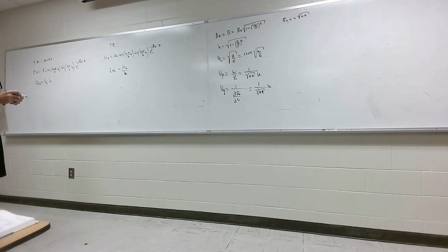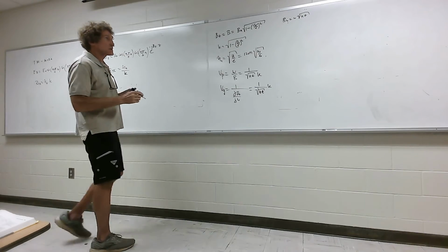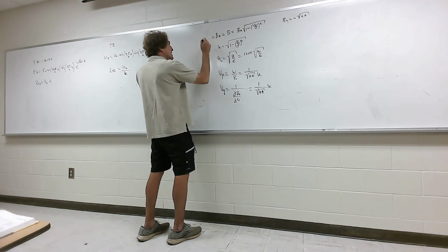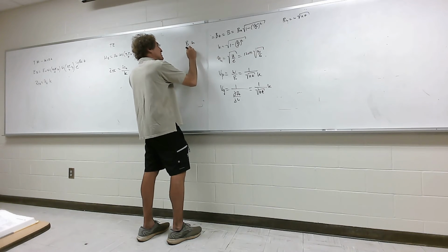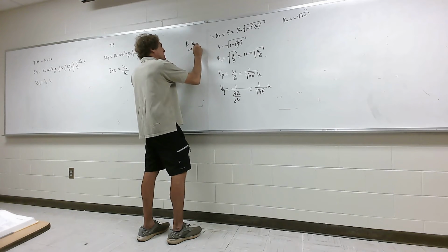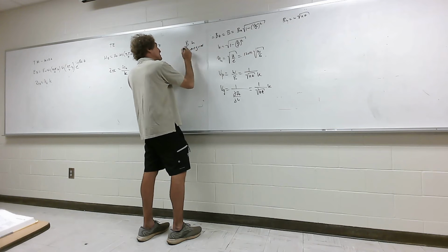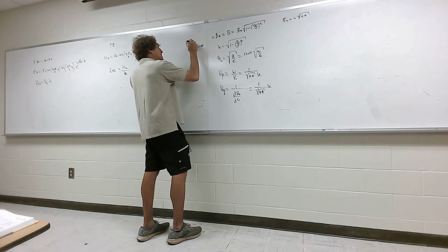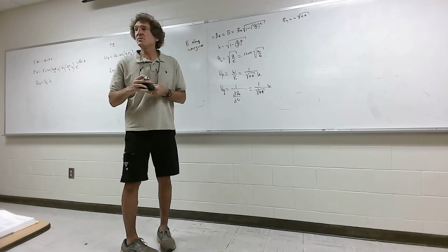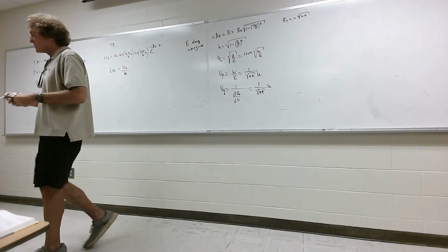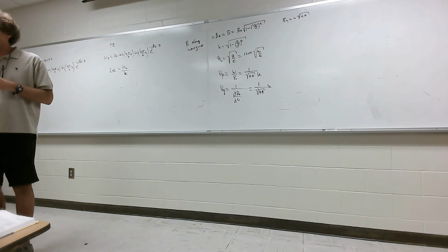All right. And I want to say one thing. This beta_z is really beta in the waveguide, or along the guide. Maybe you can call it beta along the guide. It means it's the beta that you would use in the standard waveguide equations to govern the impedance of a waveguide.